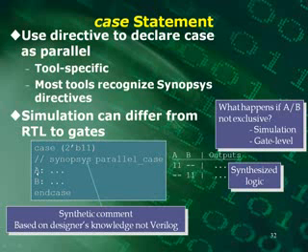Are these compiler directives? Yes, these are compiler directives, synthesis directives. Are they always in comments? These are special things that some vendors have come up with, embedded in comments. It's not part of the Verilog language.